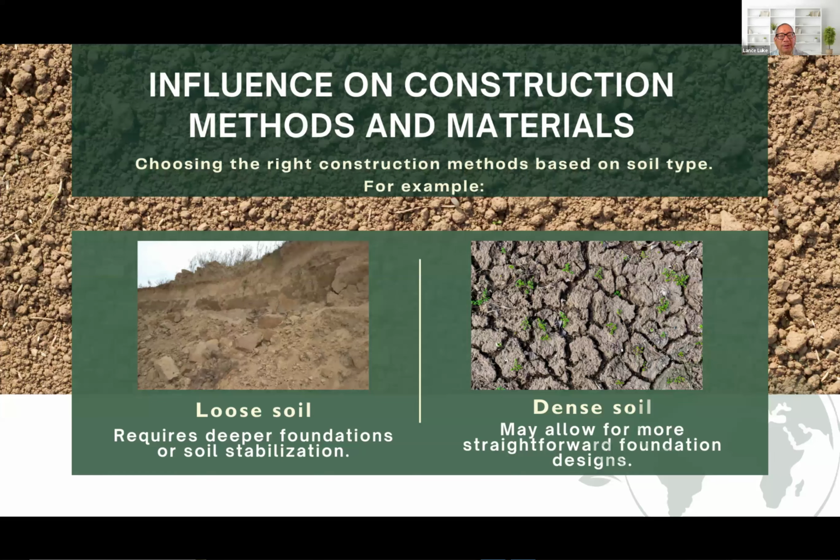The influence on construction methods and materials. You have loose soil, which requires deeper foundations or soil stabilization. Dense soil may allow for more straightforward foundation design. So that's the difference between loose soil and harder soil.